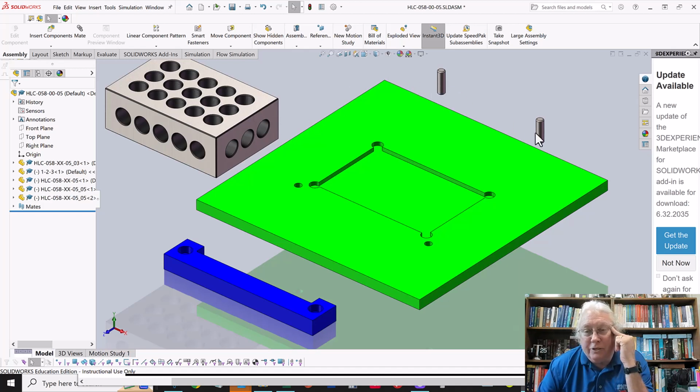These are gauge pins. These are precision gauge pins that are the diameter plus or minus probably a few tenths of a thousandth of an inch. And we're going to make those diameters the maximum material condition of the counterbore holes in the part. And you'll need to again go through those lecture notes to learn about maximum material condition, what that means.